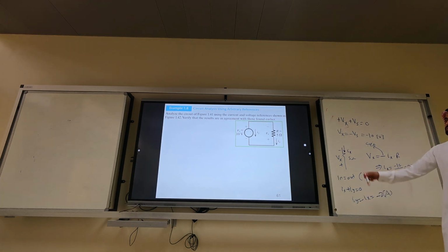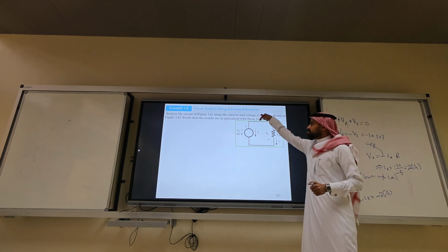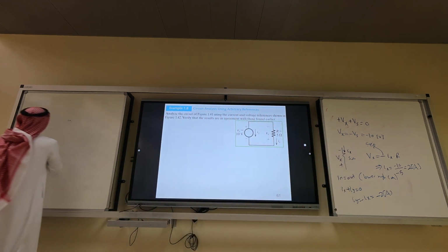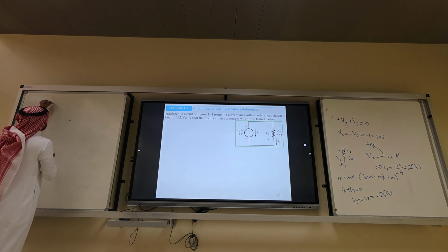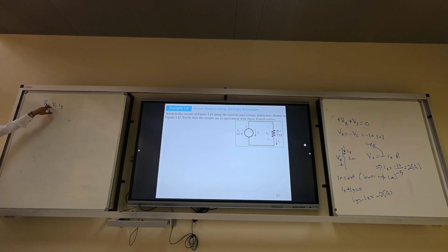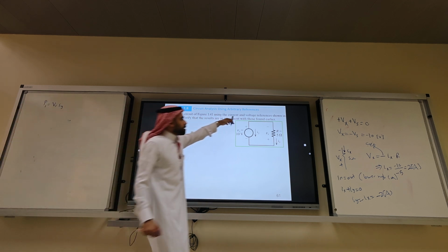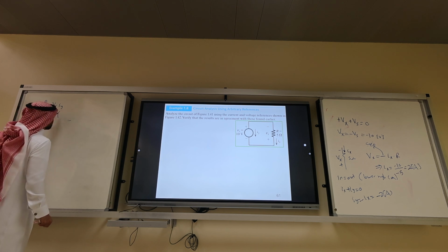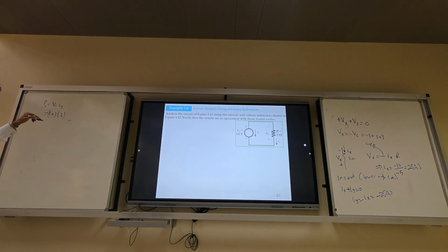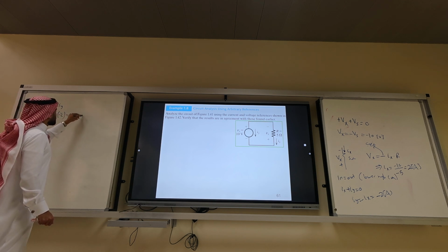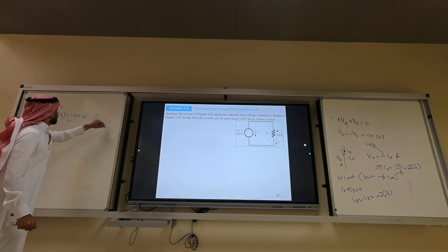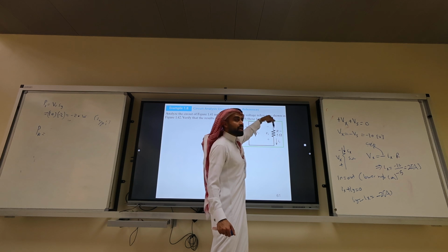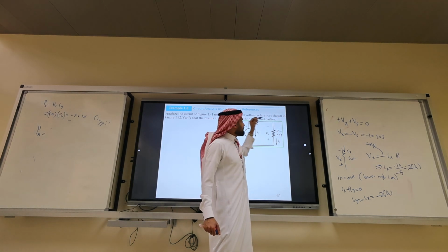So what's the power? Vs is minus 10. What is Ps? Vs times Iy, right? No negative sign because the current enters from the positive, which equals 10 times 2. 2 or minus 2? Minus 2, which is minus 20 watts. So this supplies, okay? What is the power across the resistance? The current enters through the negative, passive sign configuration. I think that's option 4.